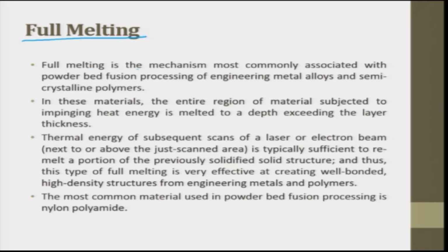Full melting is the mechanism most commonly associated with the powder bed fusion processing of engineering metal alloys and semi-crystalline polymers. In this mechanism, the entire region of material subjected to impinging heat energy is melted to a depth exceeding the layer thickness.